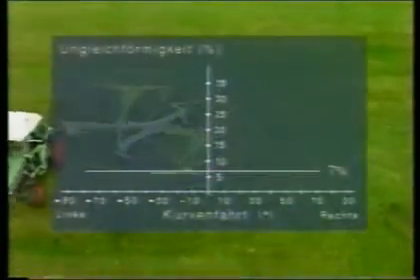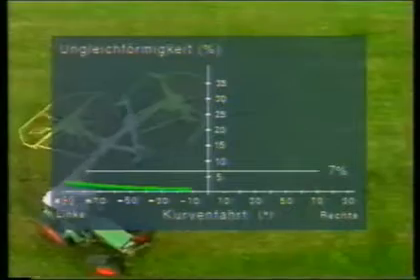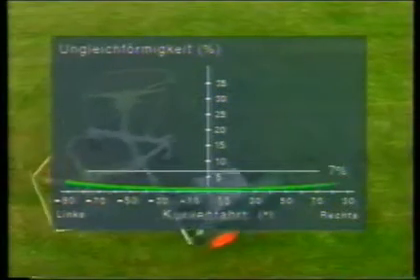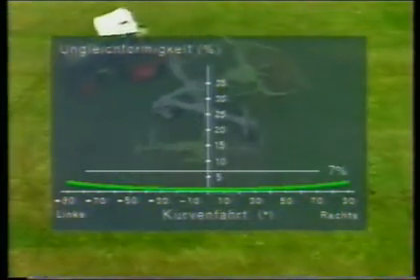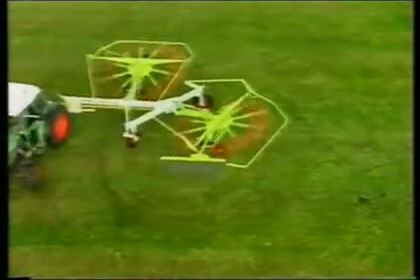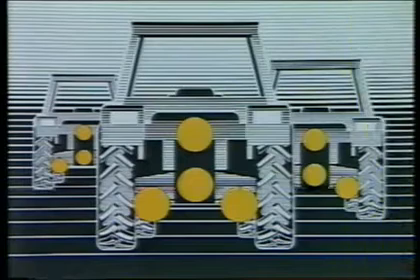In order to avoid oscillations in the case of unilaterally angled PTO drive shafts, a constant velocity joint must be used. The Walterscheid 80-degree wide-angle constant velocity joint transmits a uniform rotary motion over the entire swivel range.